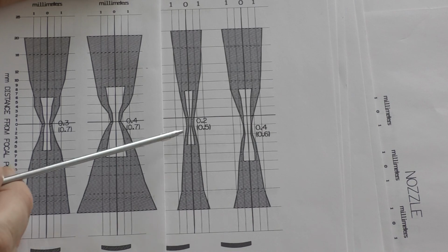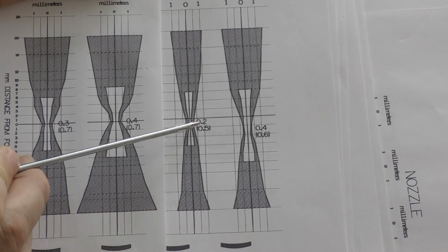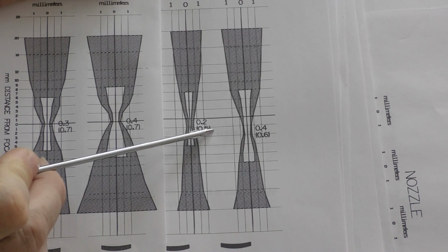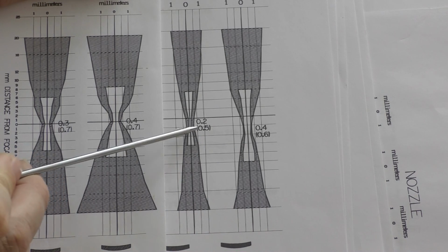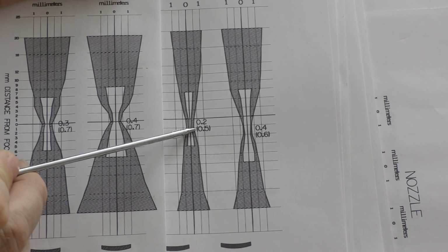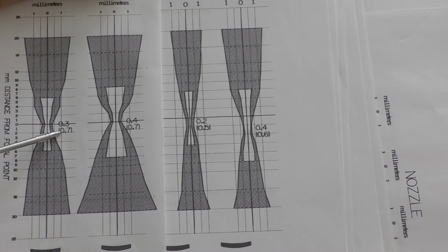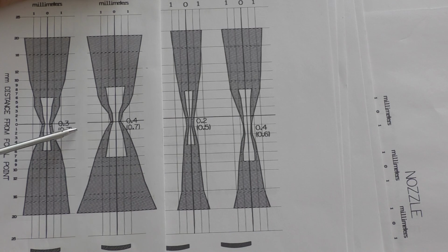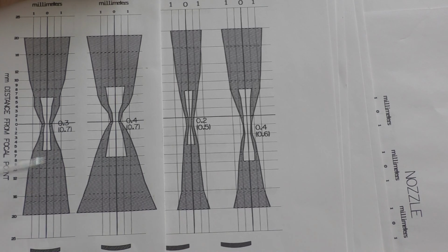With this low power map, we've got 0.5 plus maybe 0.1, so we may have a 0.6 neck across there. We've got 0.7 here, plus maybe another 0.1 or 0.2, I don't know. But so the same rules apply. The more power we try and push through the lens, the bigger the spot size.